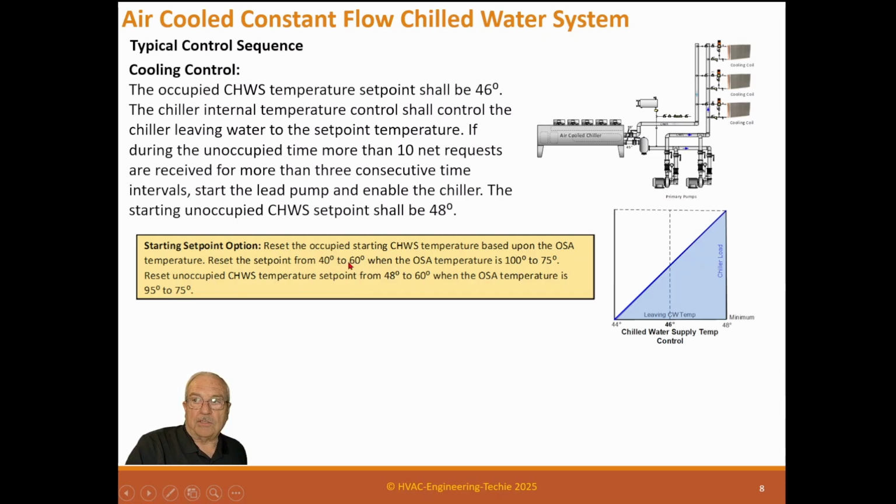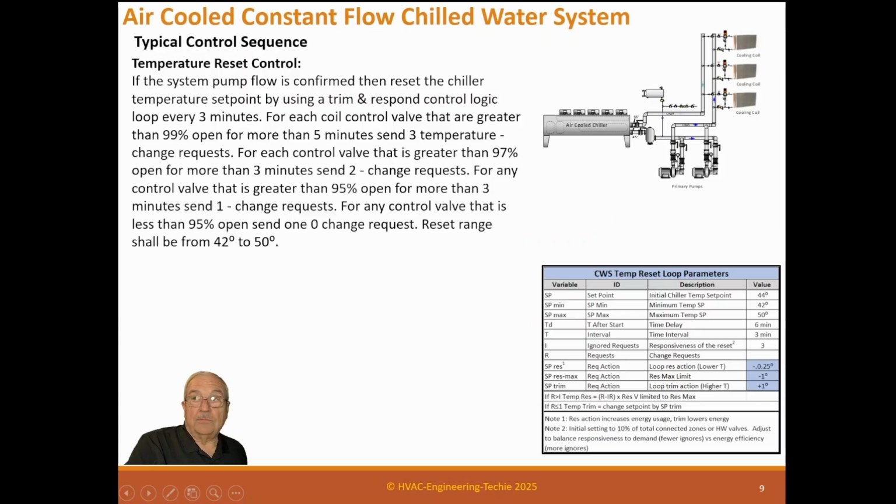You know, if you think this is too cold, then it can go warmer. So I set it down to 40, which is the minimum supply temperature. You really should never go below 40 because you're getting right close to a possibility of a freeze-up on the evaporator, because it has a 4 or 5 degree range, and you need to be really careful that you don't get into that offset. But that's possible too. So then when you come to work and it starts up, it's going to be at approximately the right chill water temperature set point. Or you can let reset handle it either way. It's up to you.